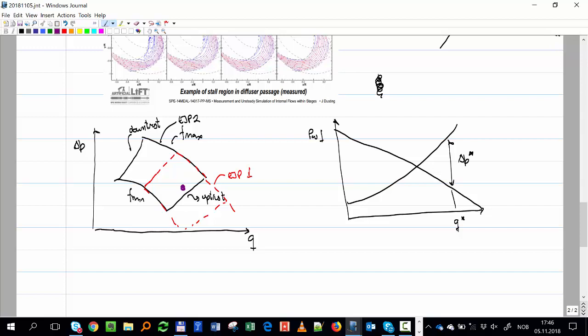Because you say, well, I have to check first where is the best efficiency line, right? But it will probably be much better than 2, right? Because here I'm very close to this upthrust line. That means that if I want to change the rate even a little bit, I will already be operating out of the envelope. Huh? We are? Yeah.